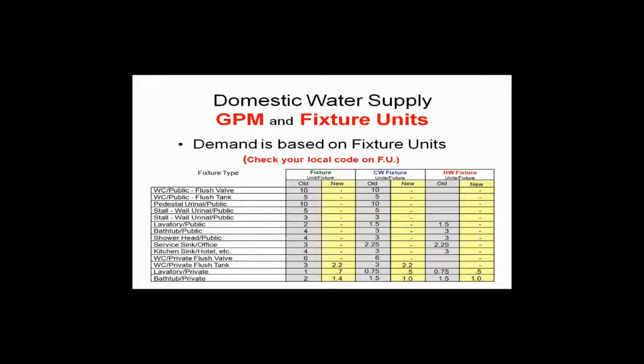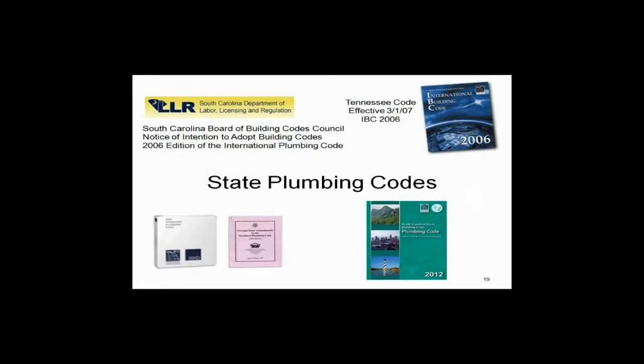So now we got the fixture count. And with a pressure booster, we're looking for what? The total flow. Once the water gets to the apartment, they can break it down to hot and cold. I've got to have the total number of fixture units. So that's all I'm really worried about at this point in time. So where am I going to get this from? I'm going to go to the local plumbing codes, and here's some typical examples.